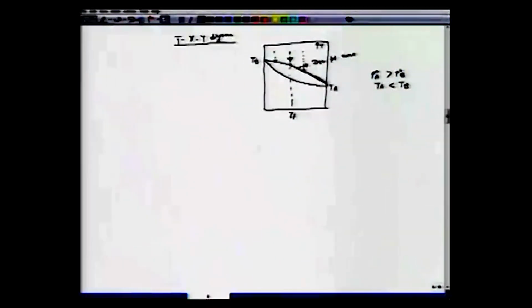All right. So now if you further cool from here, then we will get a liquid and vapor mixture here. We can call this XA. We can denote this as YA. The idea here is that the amount of liquid formed will be in the ratio of this by this. So it's a tie line, and we can apply the lever rule which we discussed in the previous slide.